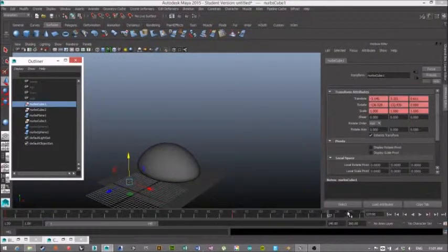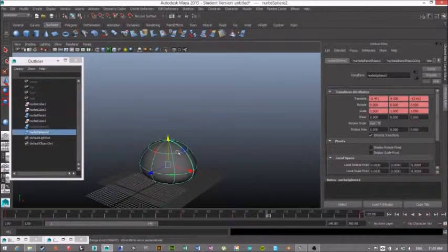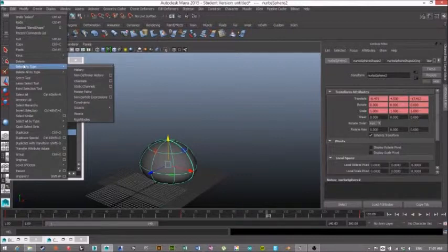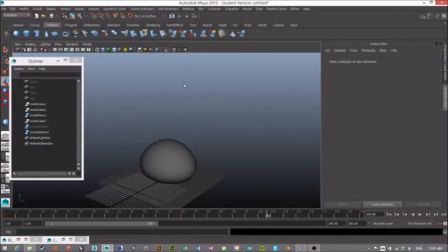To that though, say you're doing some sort of exploration with blend shapes and you're like, okay, I modeled this shape and I modeled this shape, but I really like this shape. This is super compelling for whatever reason. It's just a piece of geometry. You can go through edit, delete by type, delete history, and then you can export that geometry into Rhino. But you can't actually export an animation.